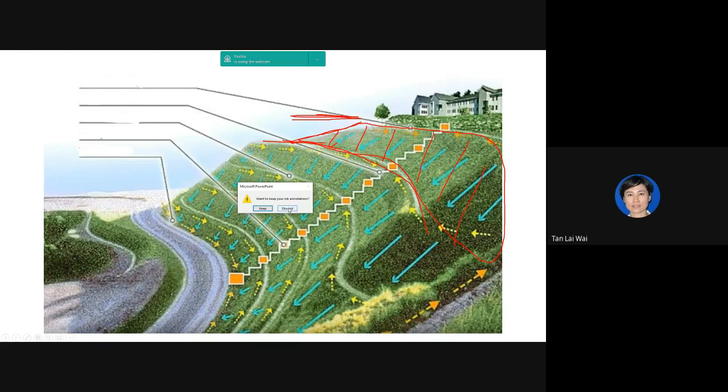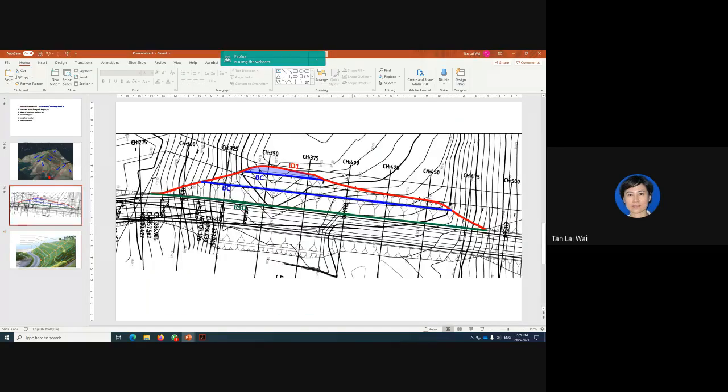But I don't mind if, for the purpose of just learning, you just get the plan area. Of course, this is a limitation that you should have written in your report, how you get the area, because when I or your lecturer interview you during assessment later, you should explain how you get it. Now, the tough part would be to imagine how you are going to determine the catchment area for the interceptor drain, because it's not so direct.